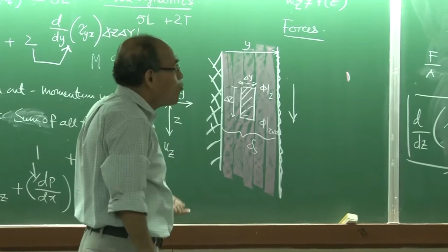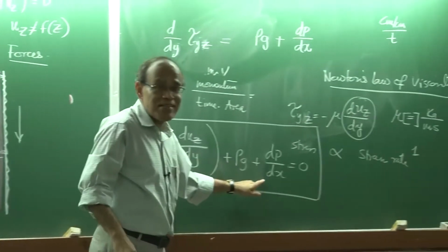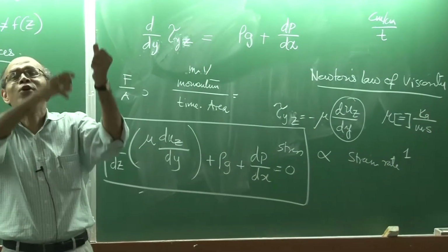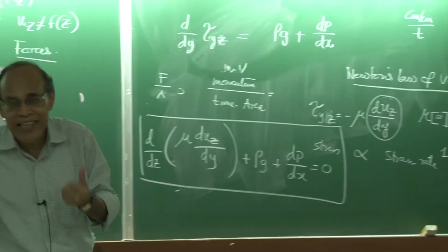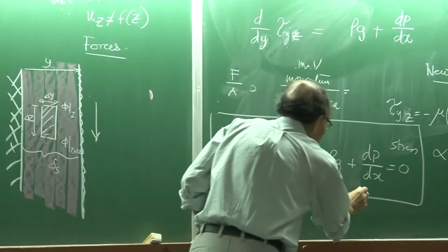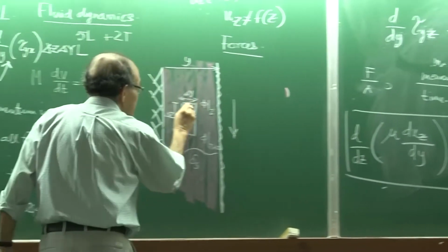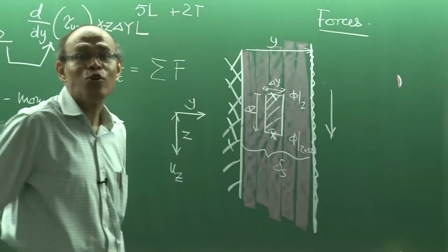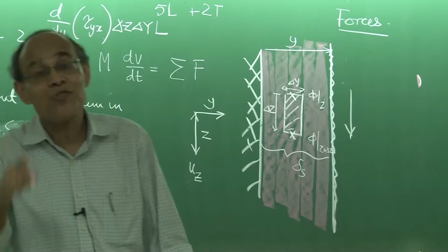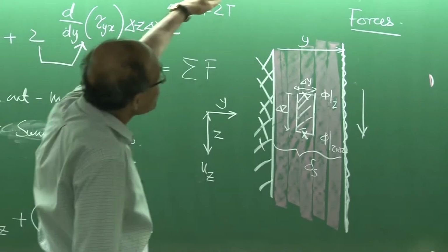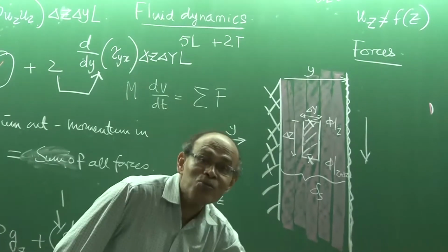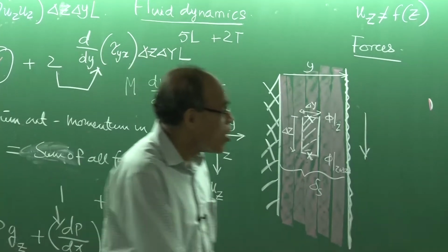Therefore, we can expect that in this particular case there is no pumping of fluid, so there is really no pressure gradient that develops here. So, the pressure on this surface and the pressure on this surface of the control volume are really expected to be equal. There is no pressure gradient because at the top surface the pressure is 1 atmosphere, and at the bottom surface also the pressure is 1 atmosphere. So, this term can be